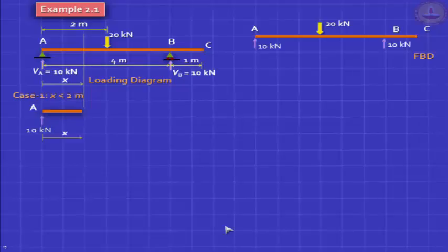You can draw two sections. One is to the left of that load and the other to the right of the load, in the overhang region. So if you take the first section, mechanically you draw two things first. Once you draw this using our sign convention, you draw V and M. This is our sign convention: positive sign convention for V, positive sign convention for M. Just do it. And I showed you in the last lecture, you could take either the left side or the right side, but we'll skip the right side here.